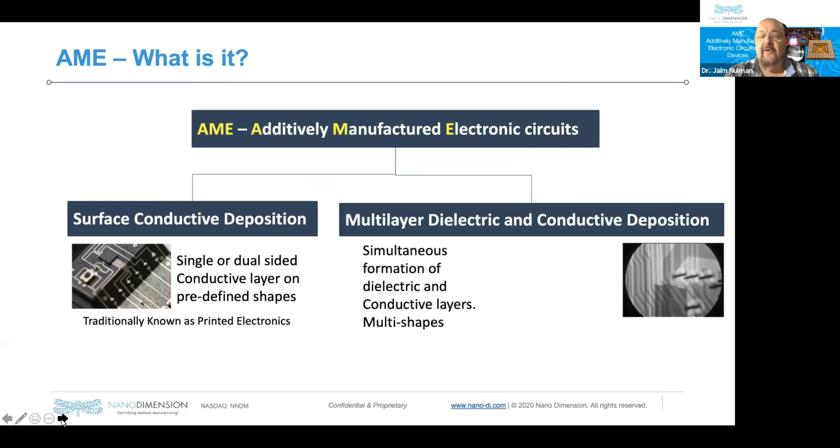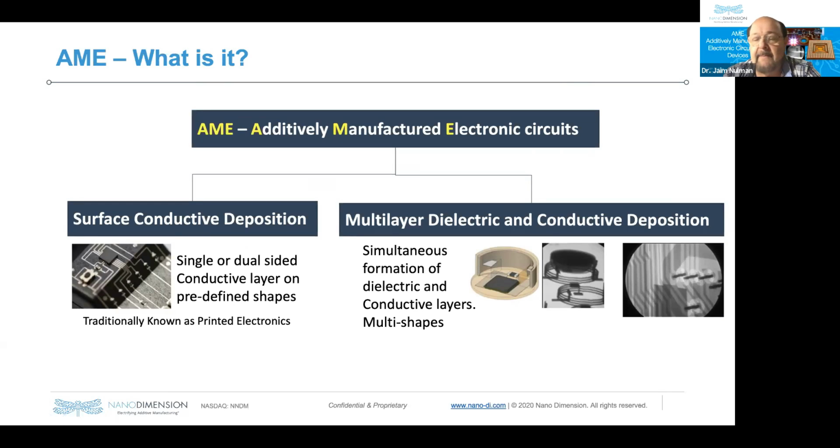What this technology allows also is to create different types of structures, which are almost complete electronic circuits. In this particular example, this is about 8 millimeters in diameter, 3 millimeters in height. It has some capacitive coupling plates printed in there, and then mounted a BGA that includes the driver for the wireless communication as well as the signal processing, some passive components, and then we can see the coil for the RF communication as well as the socket for a battery.